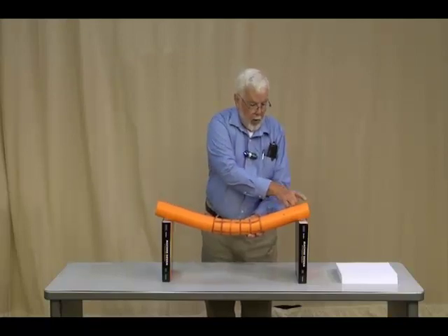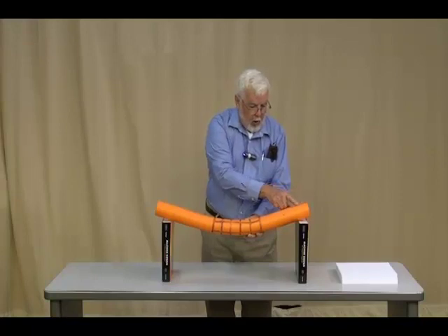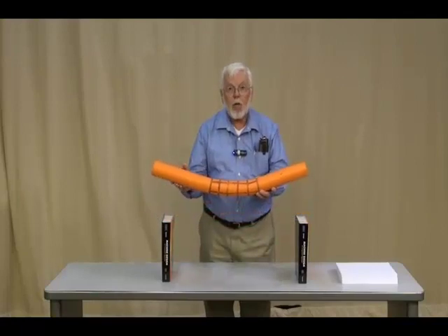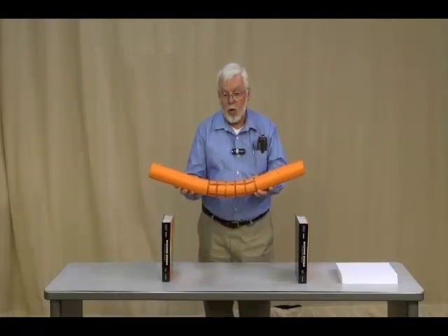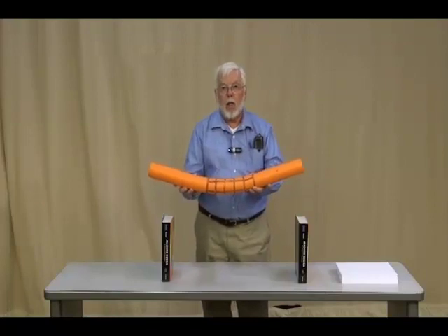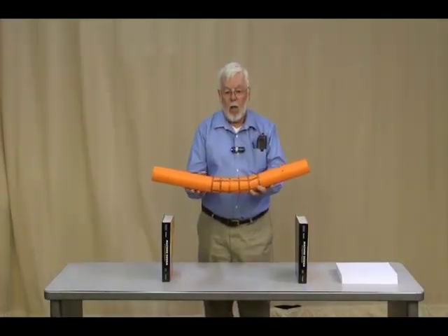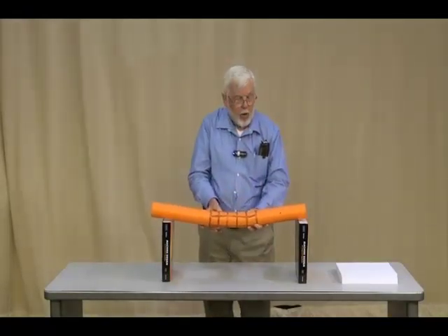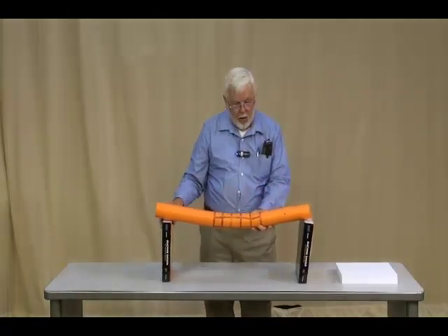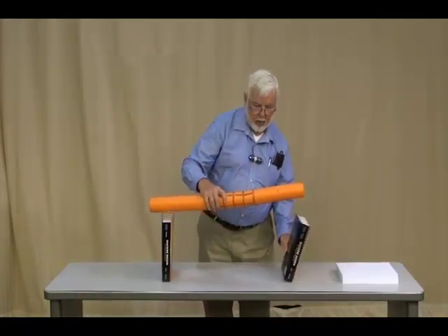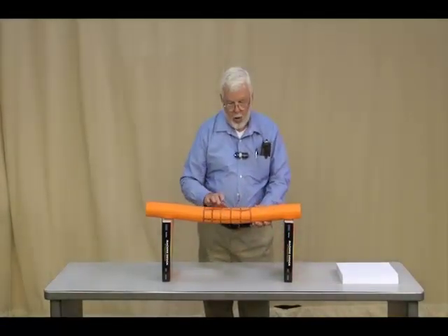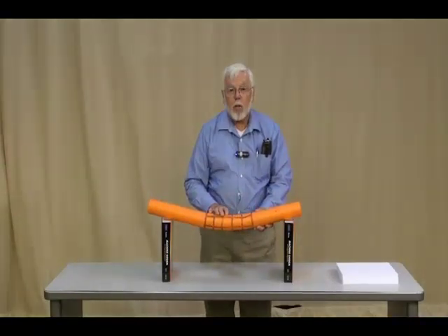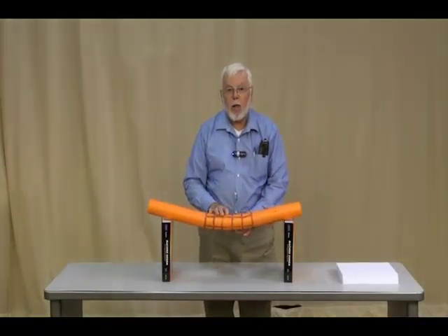And that's important to understand because it tells you what's happening to the molecules of the material inside this beam. Ask yourself, is the distance along this surface the same or different than the distance along the bottom surface when it's curved? And the answer, of course, is they're not the same because they are now at different radii. Now the radius is large, and the difference is only the thickness of this beam. But there is a difference. Therefore, the circumference of the top arc is less than that of the bottom arc. And as a result of that difference, the top surface is being put into compression, and the bottom surface is being put into tension.